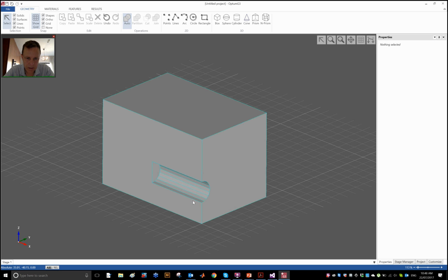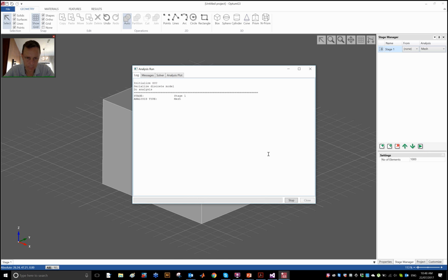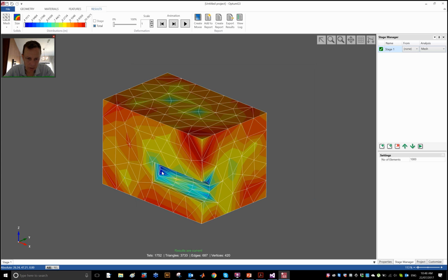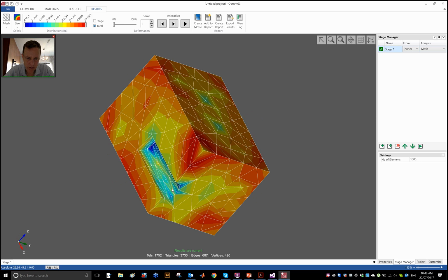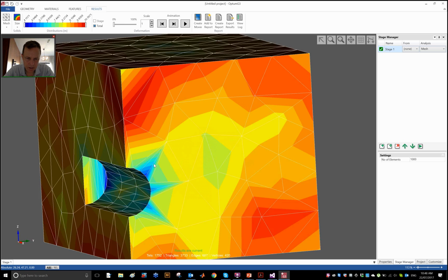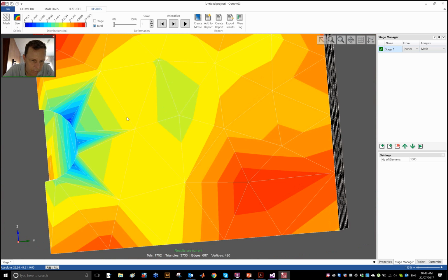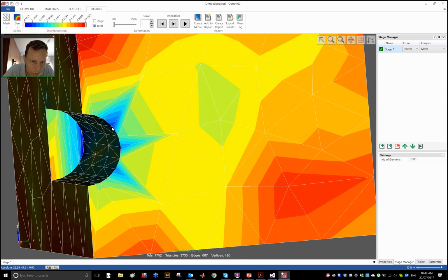So this is now my discrete circular tunnel, and let's try to mesh again. And this looks a lot better. We don't have very many elements along the length of the tunnel, which is what we want, and we have a nice even subdivision of the base. So all the segments here are of the same size.